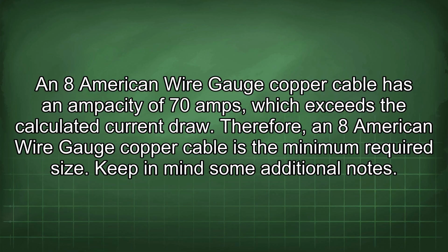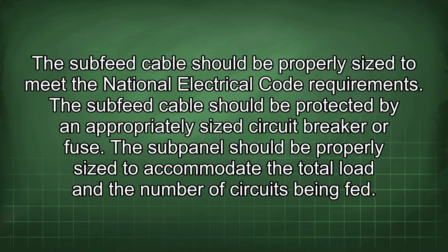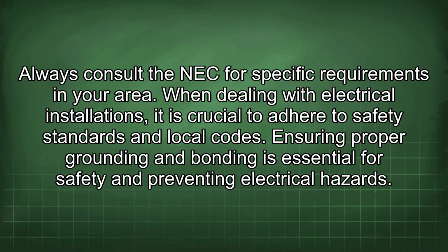Keep in mind some additional notes. A subfeed cable should be properly sized to meet the National Electrical Code requirement. The subfeed cable should be protected by an appropriately sized circuit breaker or fuse. The subpanel should be properly sized to accommodate the total load and the number of circuits being fed. Always consult the NEC for specific requirements in your area.